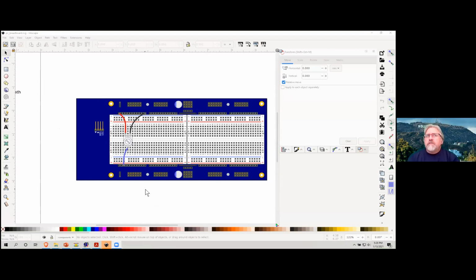Now, we'll have to do different pins. One of the things that is unique about the P2 is that we have the smart pin serial, and that's a blessing. It also creates a restriction, because if we want to use a smart pin as a UART, then it can only do one thing. Whereas in the P1, we're using a cog to do our serial.